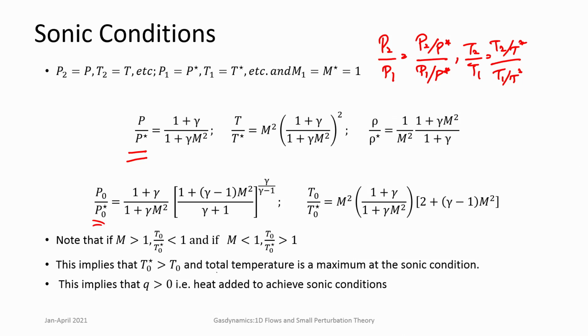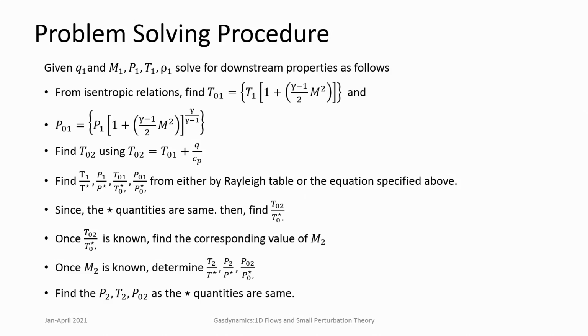So, that is the ease of using this reference condition. In Rayleigh flow, the flow always drives towards a sonic condition. So, always heat addition achieves sonic conditions.